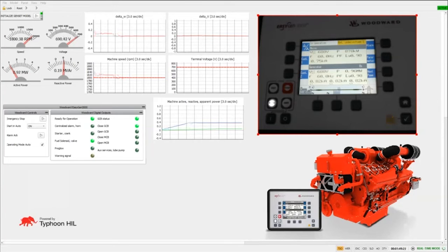So now we can play around with the controller, change some power, ramping up, ramping down, and so on. Also, there is the possibility to use some communication protocols such as Modbus. So we can also use some third party, let's say a microgrid controller, where we can send some power reference to it.